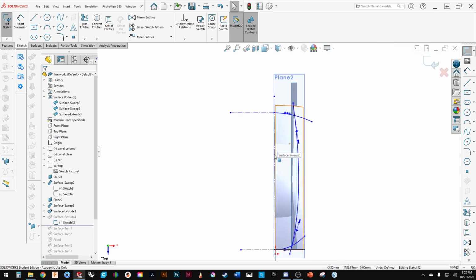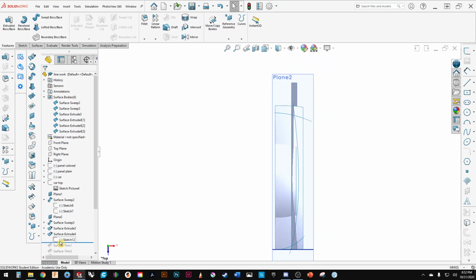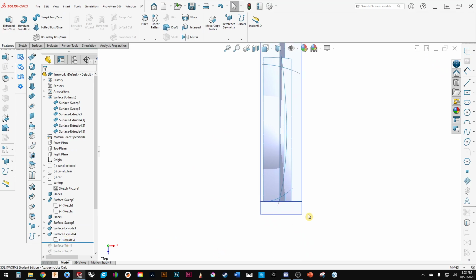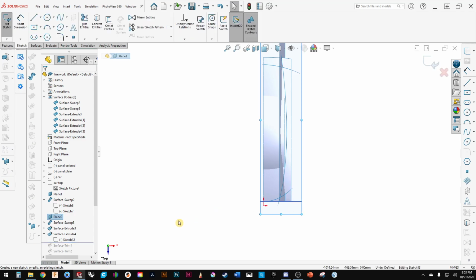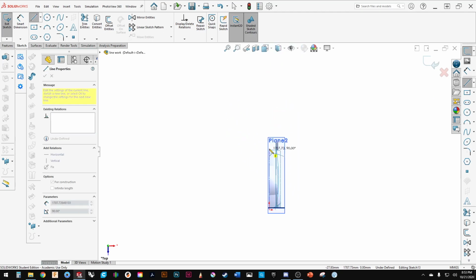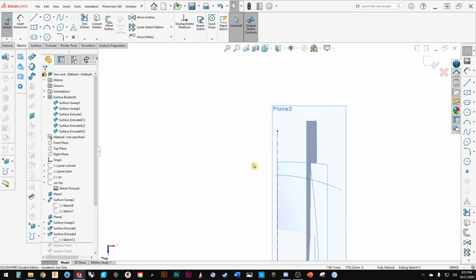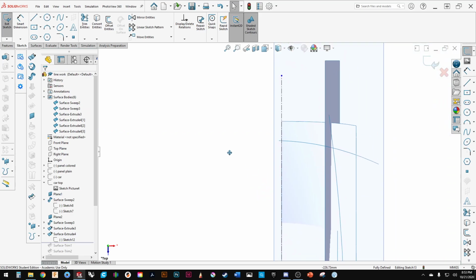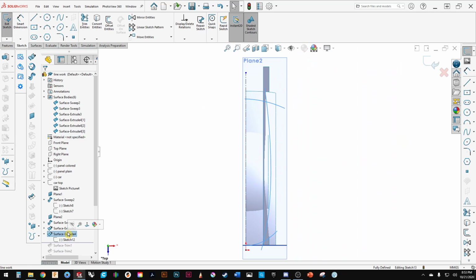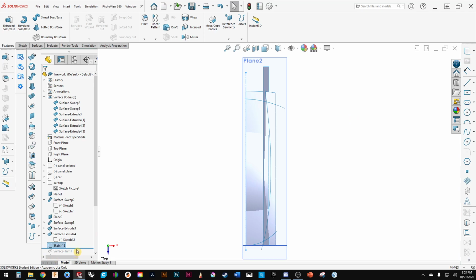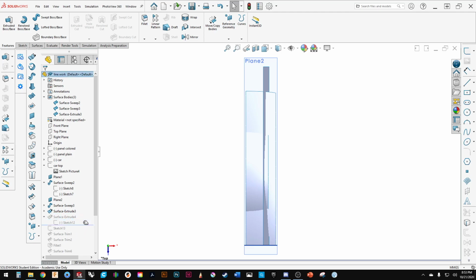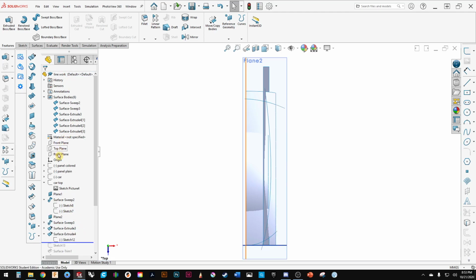There'd be a difference, I would think, at least. Lately, what I've been doing sometimes, just to be on the safe side, if I'm lofting between 2 or 3 or more cross sections, rather than draw half the cross section and then loft it and then mirror it, often in the sketch I'll just mirror that, and that way I know for sure when I loft between each one that it'll be tangent, because it's lofting the whole section and not just half.